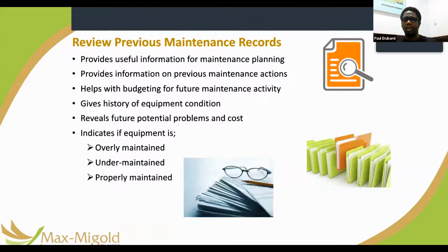If I'm managing a large piece of equipment, maybe a massive chiller system or air handling units, and I realize that the compressor has been replaced only recently, that means that component is new, right? That component is very solid at this point. So my maintenance plan will be laid out with the understanding that I'm not going to have a problem from this one, at least for a number of years, because that's what happens with that particular type of asset component.